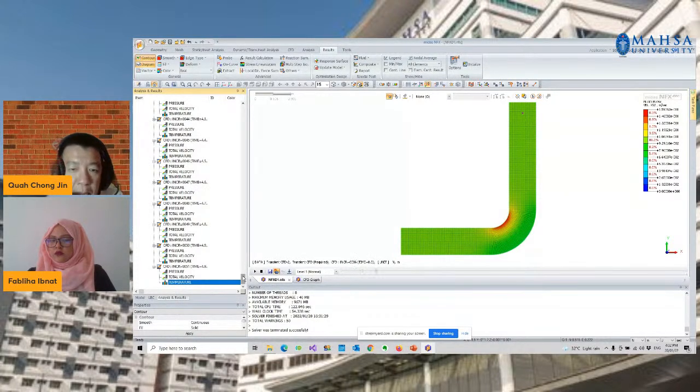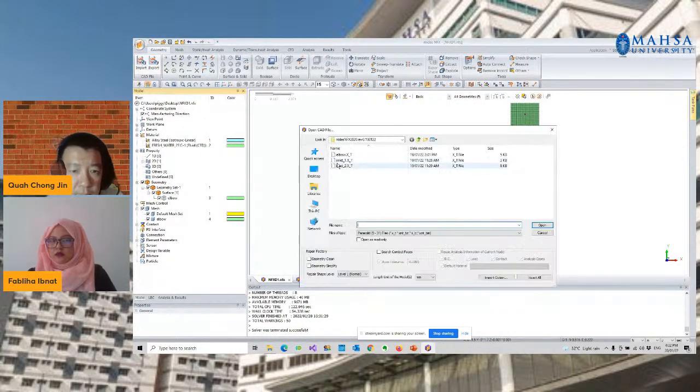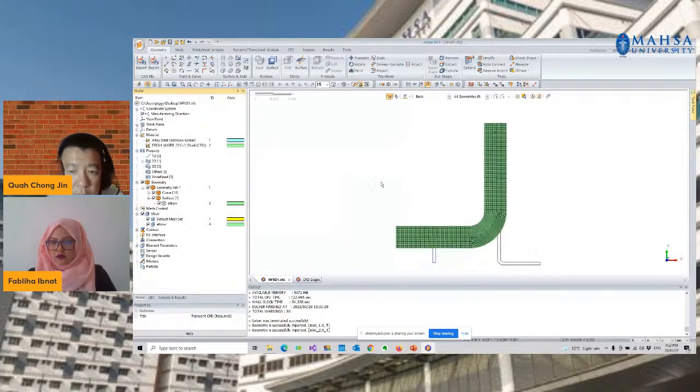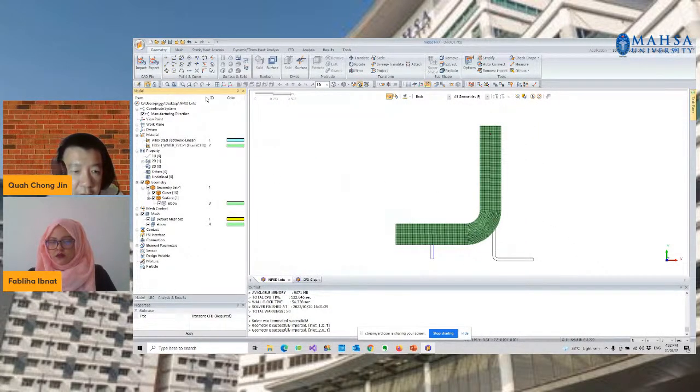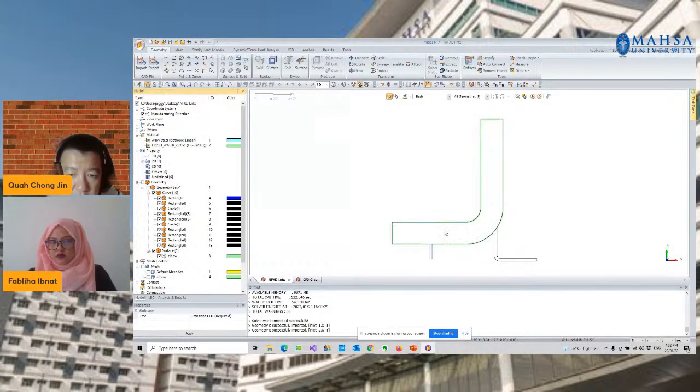So we will be doing some modification in order to inject two more inlets now. We'll go back to the design mode, and what I'm going to do is import the two inlets, inlet 1 and inlet 2. Okay, so you'll be seeing these two extra inlets. We have this curve, we have this surface. And let's switch off my mask.